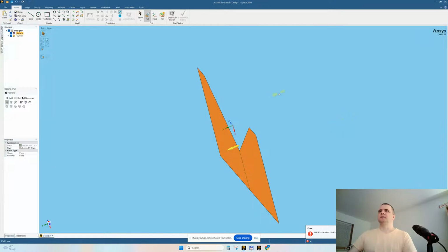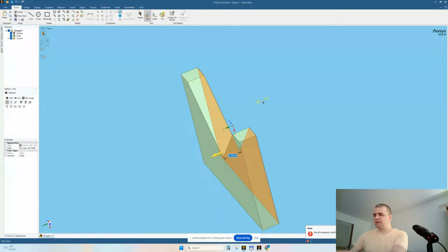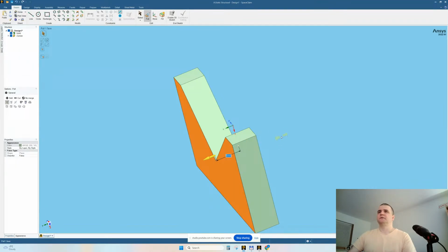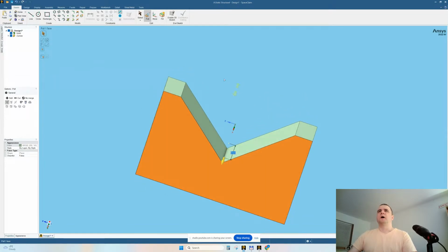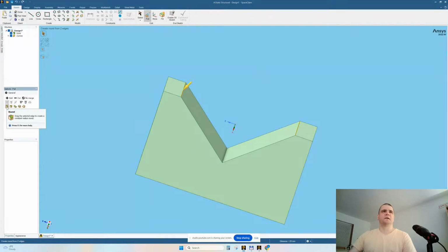Let's extrude a little. We are proving a point. This is for tutorial purposes. Let's not make it too thick. 5 millimeters is more than enough. So I was talking about some fillets. These two, yes, are in the Pull command, and the Pull command has many options. The first option is the fillet, the rounding option. We drag and drop, or we can write a value. Let's write 1 as a value.